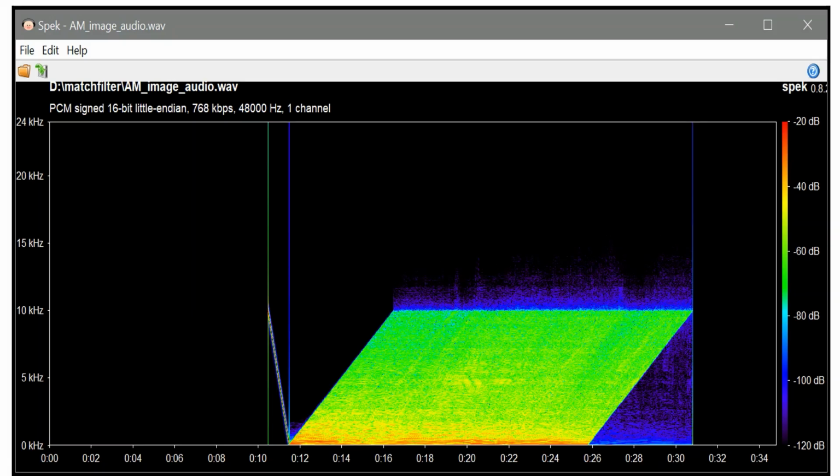And here's a picture of the actual final WAV file that you would send to your transmitter. Or you could just send it as a baseband through a telephone line or something. You don't really need a transmitter, but I figured this can be either a wireless or wired experiment. But here's the chirp. This is the preamble. That's what allows me to know when the signal is starting.